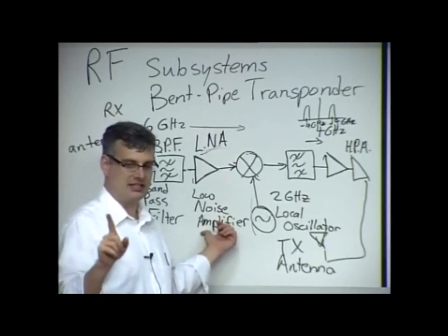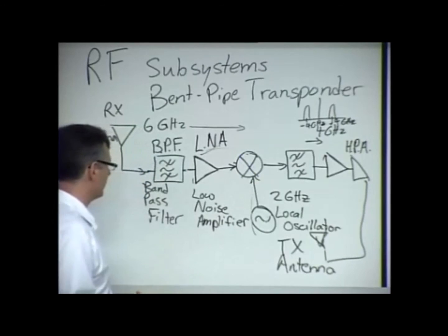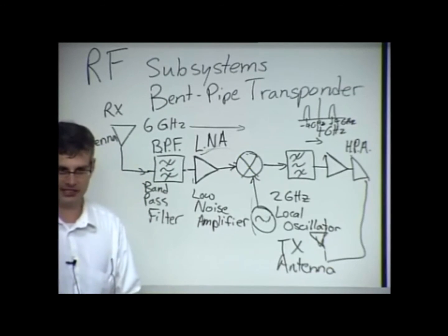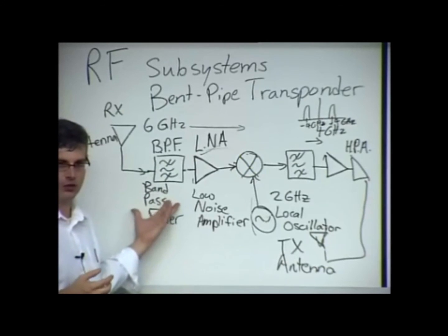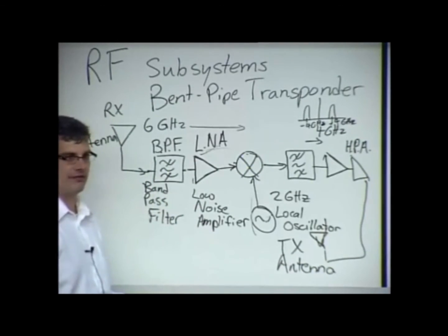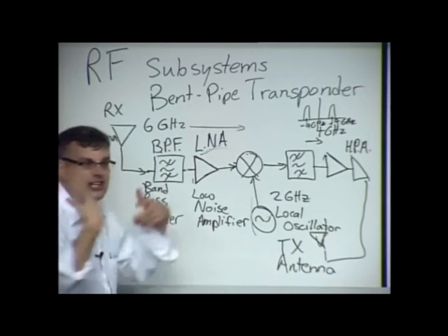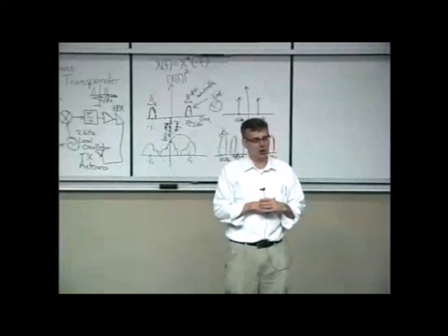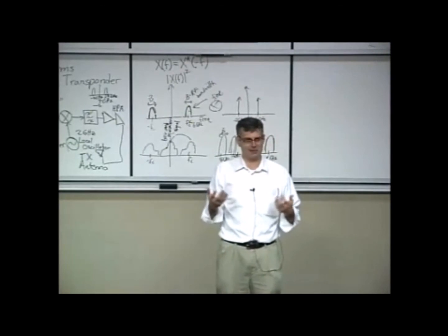If, however, and this is how most modern satellite transponders work, you use what we call regenerative repeating, you actually demodulate the waveform, decode it, get the best estimate possible of the digital bits, then re-encode everything and remodulate it and send it back down to Earth. That's a much more effective strategy. Why? Because digital communications is kind of magic.